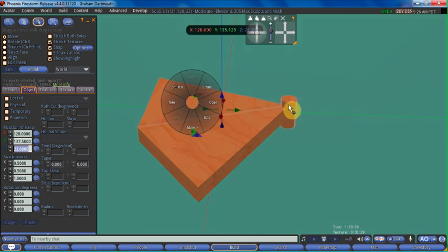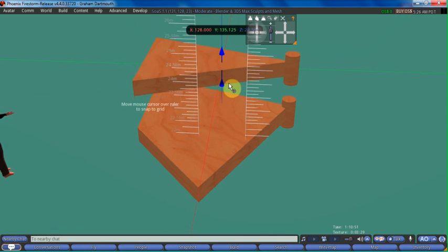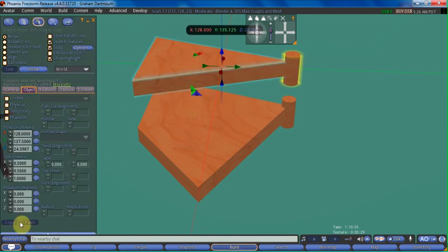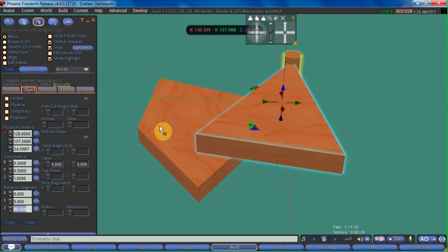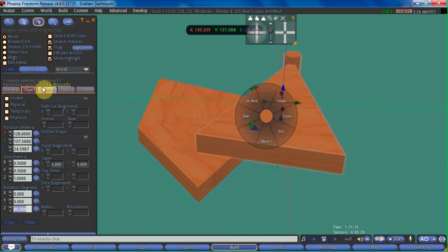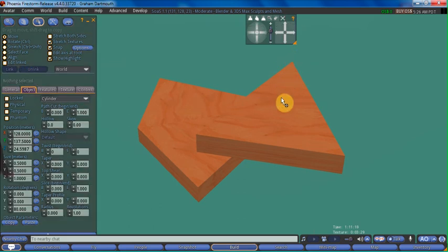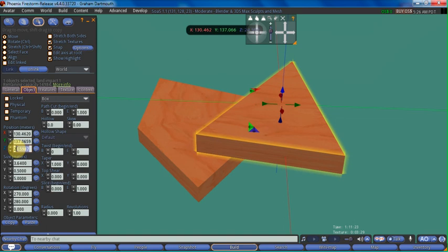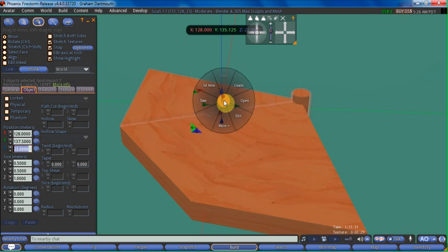Okay, now we can do this again, select the first one with the cylinder, we can shift copy upwards, if I can grab the handle. Where was I? Here we go. Shift copy upwards. Okay, now we need to rotate this again, so we know we rotated it by 40, but we're on a second one, so star or multiply by 2. Okay, then we can unlink this, we can delete the cylinder, and we can drop this back down to 23 meters. Okay, now we can keep doing this all the way. I'll probably pause the video at this point until it's done, and I'll see you on the other side.